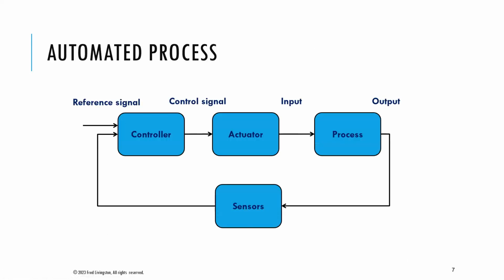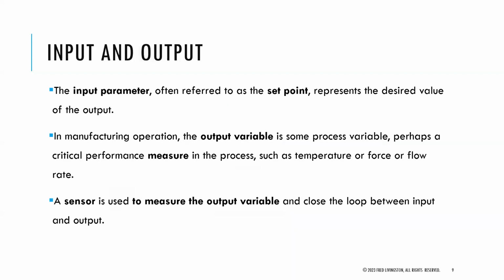And so this is our basic feedback control loop. We're mostly using closed loop in the system. So you have the controller. In this case, we're mostly using an on-off, bang-bang type controller. We're turning the conveyor on and off, or we actually use some timers. We actuated a DC motor, and then the process was the actual system itself, and then we had some feedback loop there with the sensor, an encoder, and we talked about different types of sensors in this course as well.